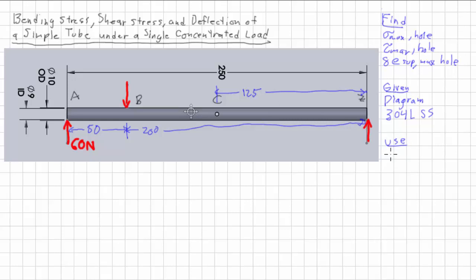First, in order to find the bending stress, or the flexural stress, we use our favorite equation, stress equals Mc over I. To find our shear stress, we can use VQ over It. Now this is the general shear formula, but we're going to simplify this in a little bit. So hold on to your hat before you use this. This can get a little hairy sometimes.